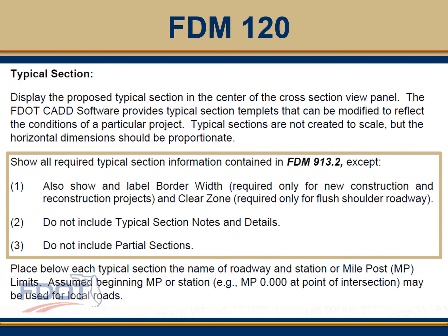Also, do not show typical section notes and details, which are developed and shown on the typical section sheets in the plans. Don't include them here in the typical section package. Also, do not use parcel sections with the typical section package.